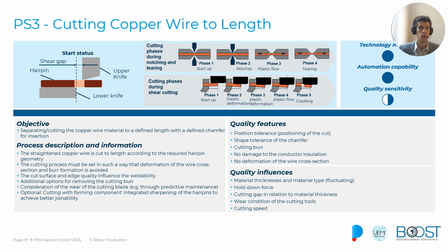And it is important that we cut the wire at the section we stripped before and not damage any insulation. If we talk about I-pins, then the pins are finished now and could be joined to the stator. For the U-pins, the next step is the bending process.